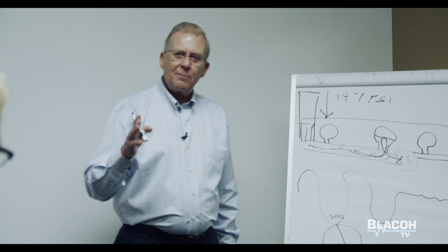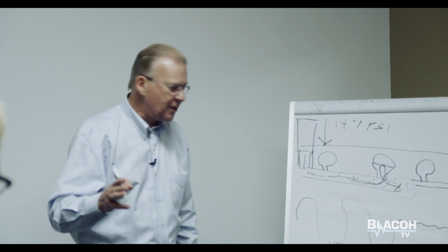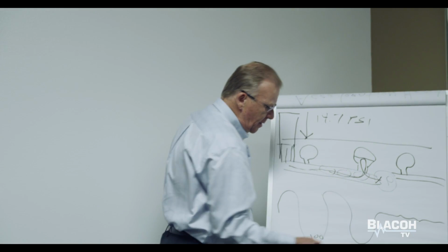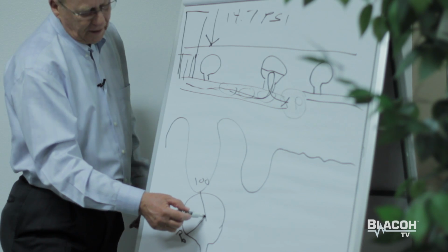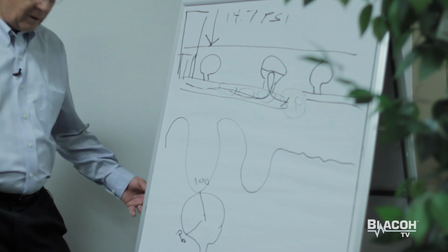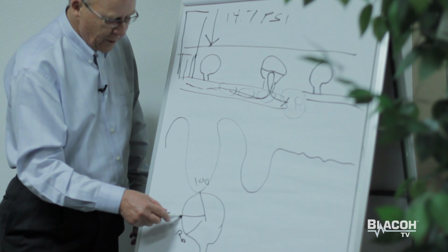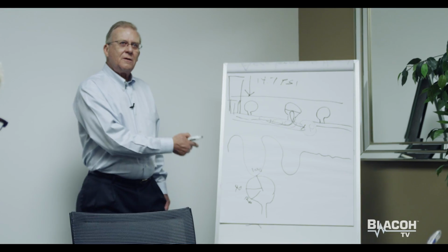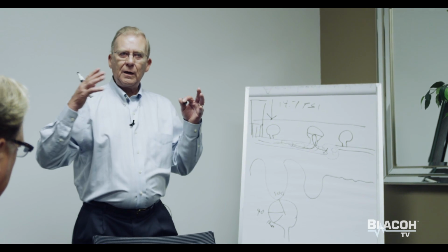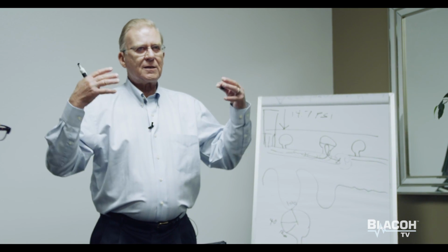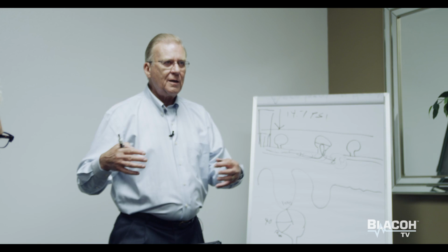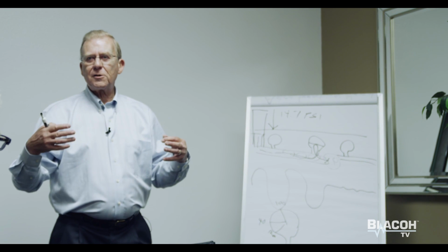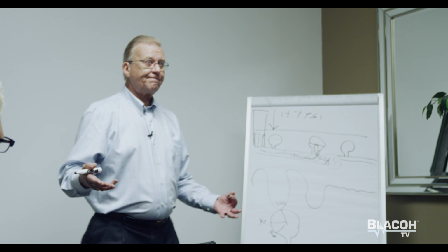But when you've minimized or eliminated acceleration head, and we have this flow, you'll reach a steady state, again, depending upon the type of the pump, number of cylinders, somewhere in the neighborhood of 40 psi. That's the true number that you would get if you size the system and figure the total dynamic head using the friction loss charts on a centrifugal pump. Okay?